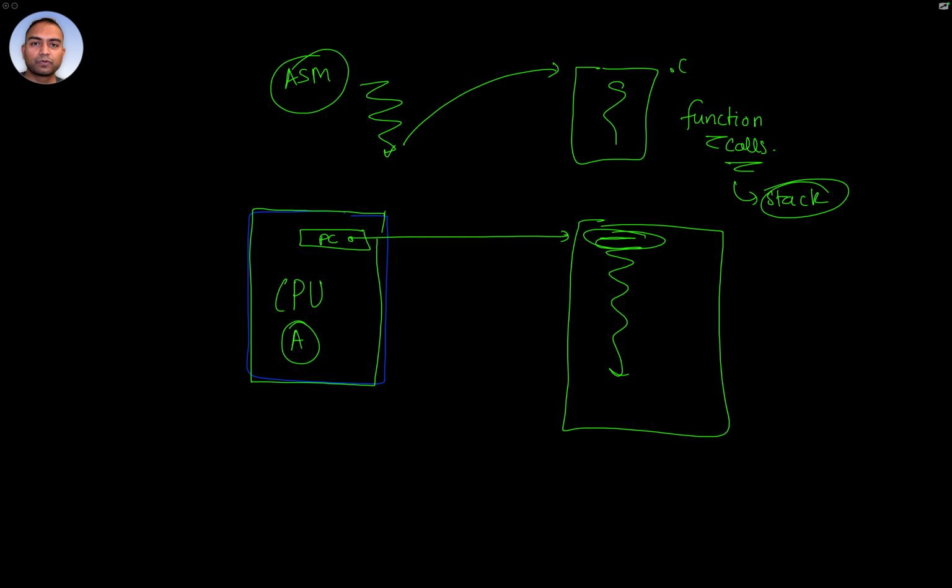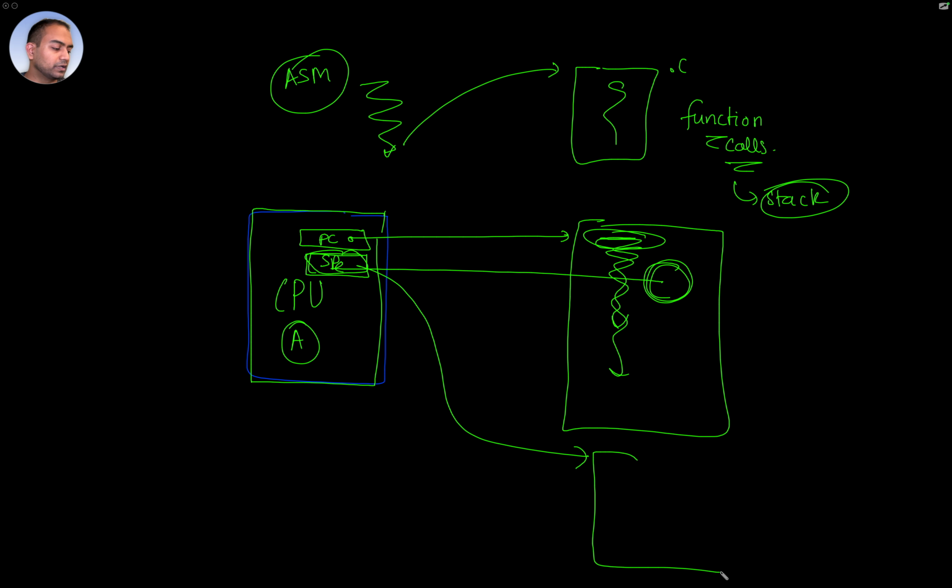And typically each processor provides a register to be treated like a stack pointer, so we have a stack pointer dedicated within the A-class CPUs. And so some part of your initial code needs to load the stack pointer with a valid memory address, so that once the execution jumps to code that requires the stack, the stack is available and the stack pointer is pointing to the right location. So these are like the two preconditions.